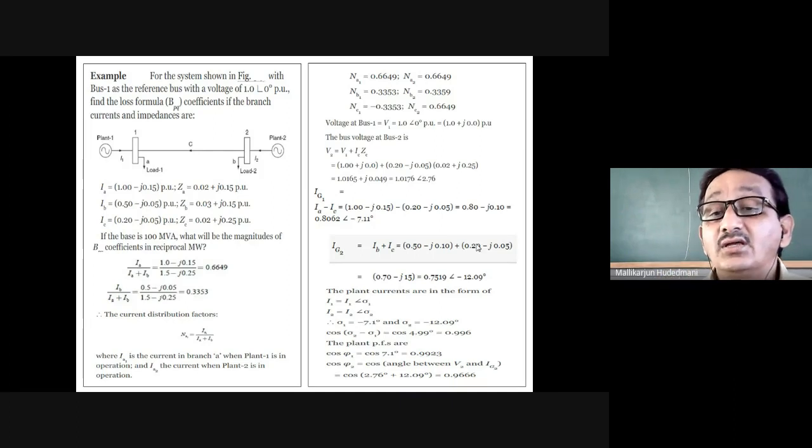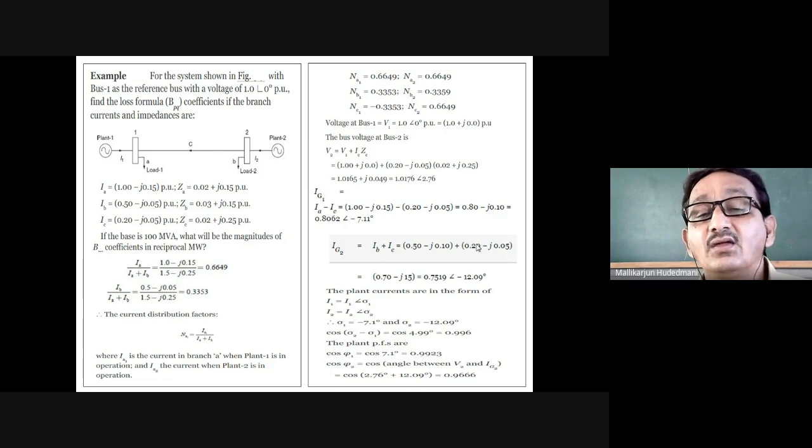This is on the B coefficient method. You have learned what B coefficients are: transmission line loss coefficients. So B11, B22, B12, B21 concern a two machine system. How are those losses calculated? You remember the derivation. What is the value of B11, B22, B12 in terms of bus voltage V1, and the transmission line resistance of section RA, section RB, section RC, like that.